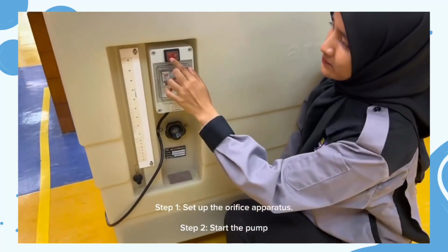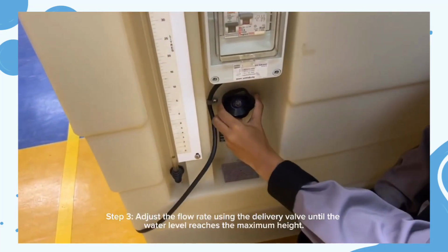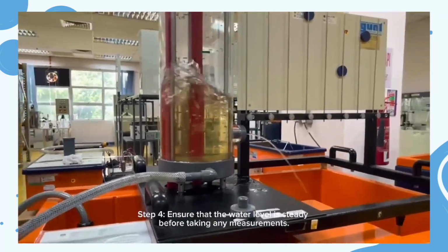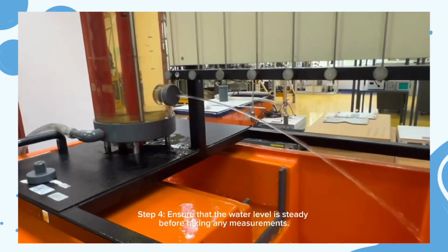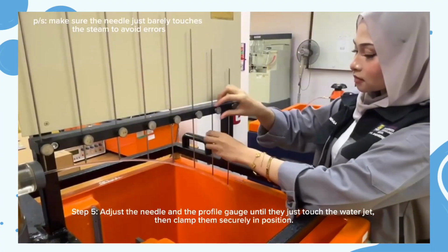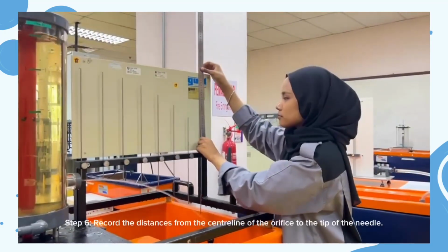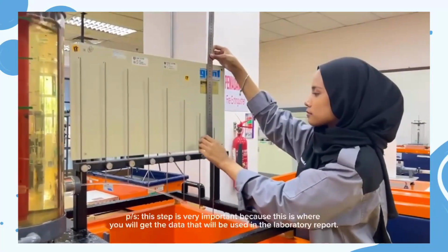First, set up the orifice apparatus, then start the pump. Next, adjust the flow rate using the delivery valve until the water level reaches the maximum height. After that, ensure the water level is steady before taking any measurement. Next, adjust the needle and the profile gauge until they just touch the water jet. Then, clamp them securely in position. After that, record the distance from the central line of the orifice to the tip of the needle.